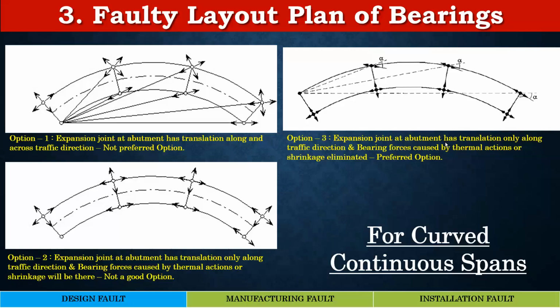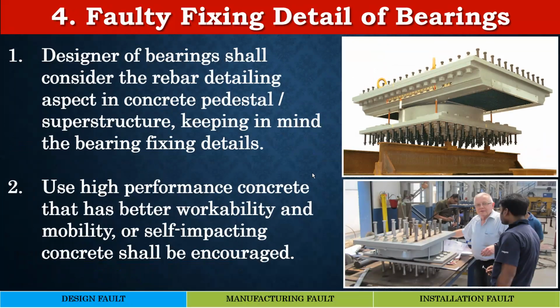Another problem that we face in bearing design is the faulty fixing detail of the bearing. We have seen on many occasions that the designer simply designs the bearing, and when it comes to the detailing of the superstructure at the junction of bearing and superstructure, or the detailing of the pedestal, the interface is forgotten about, and this is a very serious issue. On many occasions, I have found at site that while installing the pin bearings, the contractor finds it very difficult because the pedestal reinforcement does not allow for the provision of studs